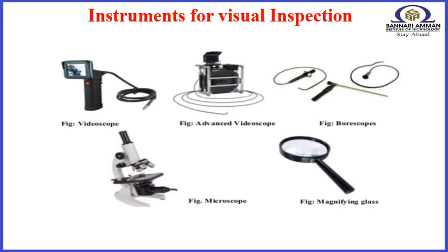Magnifying glass. Before any mechanical or optical aids are used, the specimen should be well illuminated and have a clean surface. After the eyeball examination, mechanical aids help to improve the precision of an inspector's vision. As specifications and tolerances become closer, calipers and micrometers become necessary.